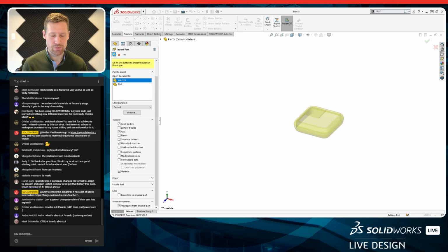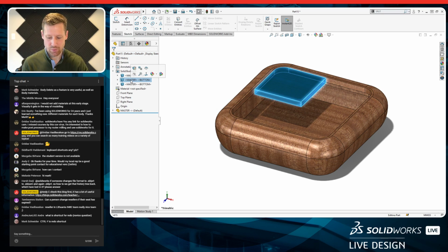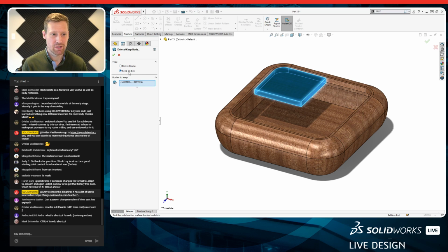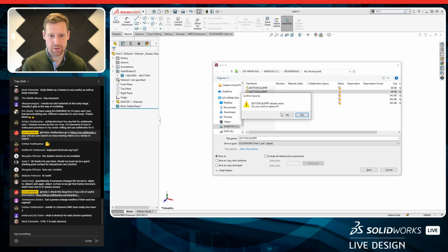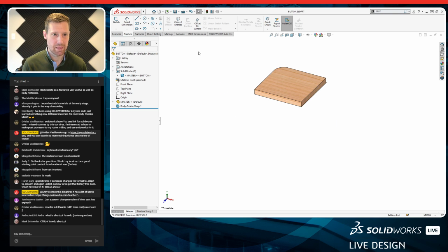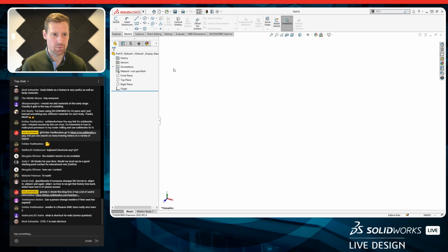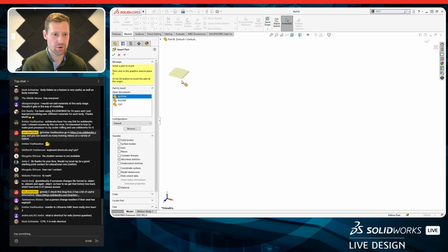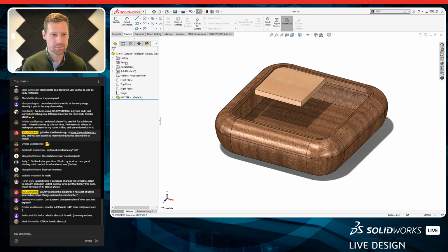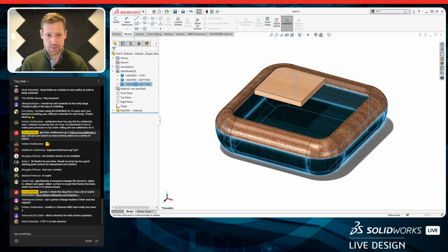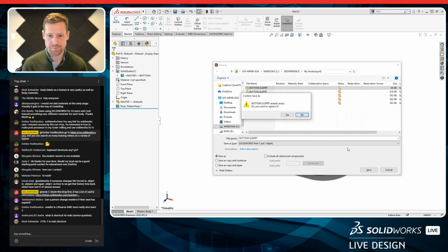Okay, so we're going to propagate those visual properties, bring that in, head over to our solid bodies folder, select the body we want to keep, hit delete on the keyboard, keep bodies, confirm. Let's save that out. And this one's called button. We'll just overwrite it, no problem. And then we got one more to do, part millimeter. All right, and then we'll do our S key, insert, and propagate the visual properties, check. Let's expand the solid bodies folder, keep that body, check, save it, and this one's called bottom.